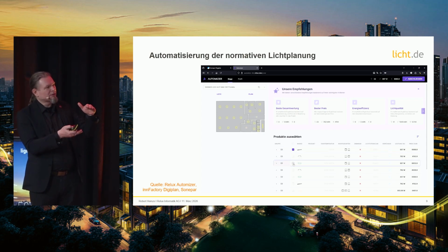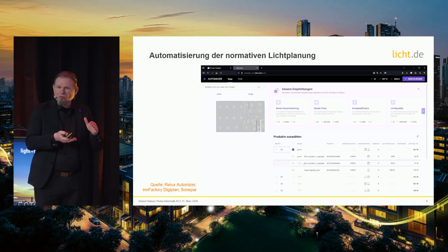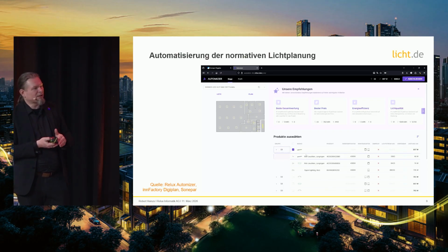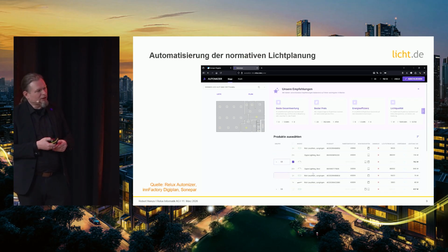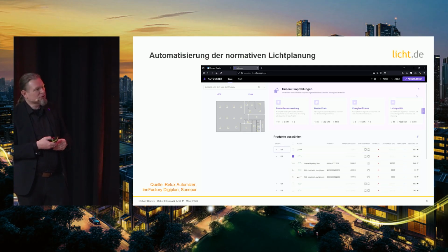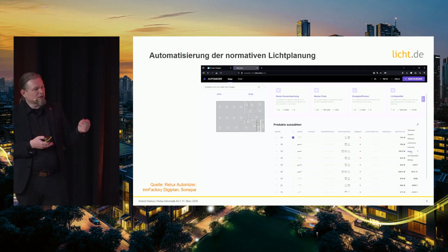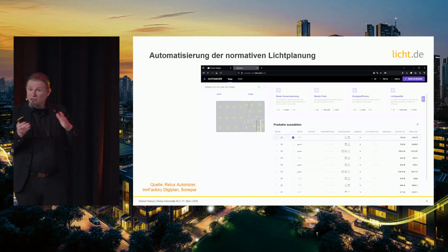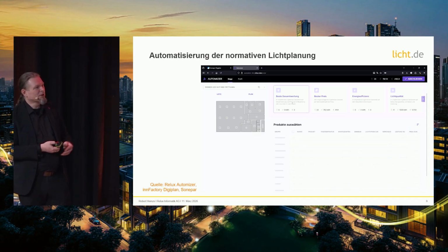And then, as a result, you get a bill of material, which covers the whole building, in this case, the whole story. And these sets of luminaires can be sorted by, classically, price or light quality. For light quality, we have a scoring system, which has more parameters. For example, glare is more important than modeling, or that's more important than uniformity, with a weighting factor. And the total score can then be sorted at the user's level. Give me the best light quality depending on my preset criteria.